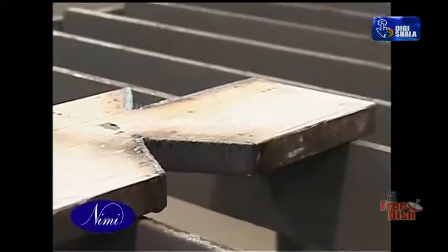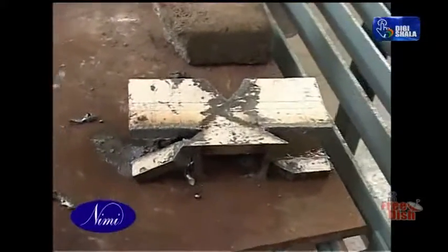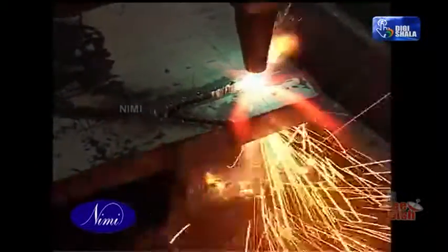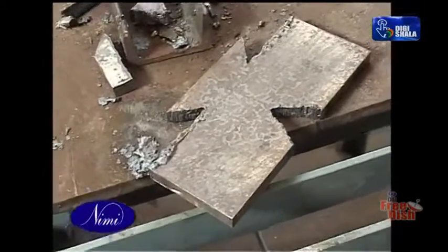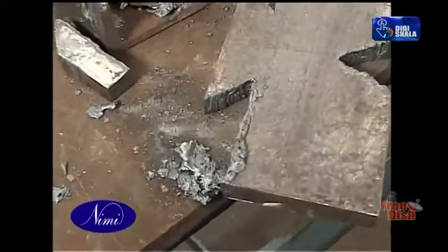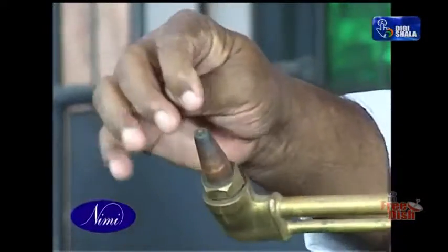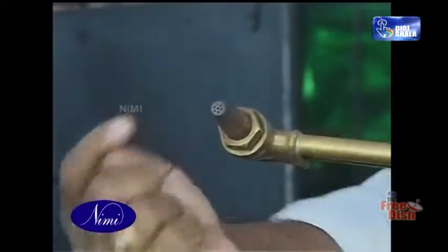The top edges resulting from the oxy gas cut should be sharp and square. Rounded top edges are not considered a good cut. This may be due to improper preheating procedures or not moving the torch at the right speed. An oxy gas cut is not considered good when the slag adheres too tightly onto the metal and is difficult to remove. The nozzle condition and the right sizes also contribute to a good quality oxy gas cut.